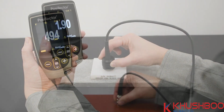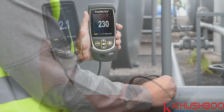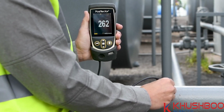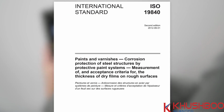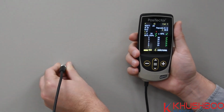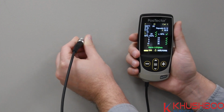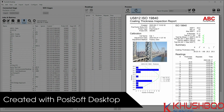thickness. When measuring paint thickness, it is important to never rely on a single reading. DFT, or dry film thickness, often varies across the surface, even at locations close to one another. A statistical approach such as ISO 19840 is often specified to determine whether there is sufficient coating thickness to meet specifications. ISO 19840 mode on the PosiTector 6000 makes the process easy by performing all necessary calculations on the gauge and creating pre-formatted reports with all required measurement data.